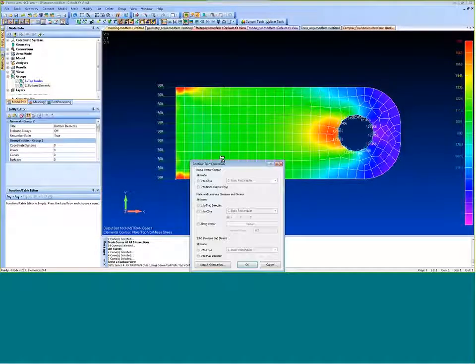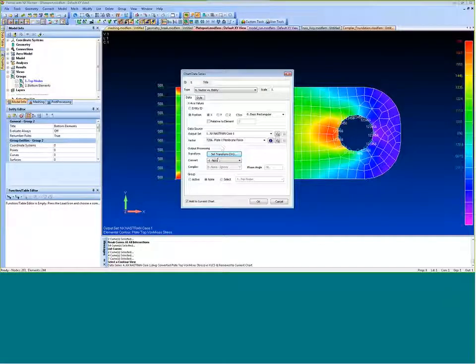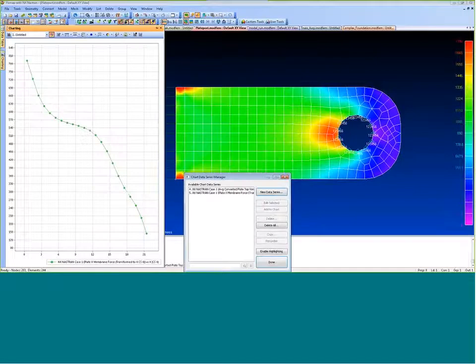And I'm going to want to transform and show it first in the basic coordinate system to get a global X force. And I'm going to select my bottom elements. And here we go. We have something kind of similar, but here you can see in the title, the plate X membrane force transformed to the coordinate system 0 versus X.